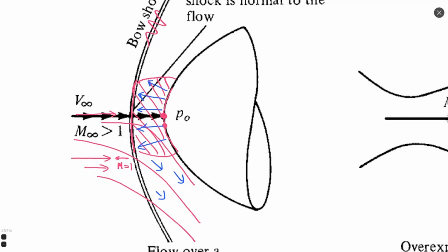We cannot see the volume of a shock wave. It's a thin surface or thin line, similar to the free path of a molecule, which is extremely thin in real flow. So we cannot say that from one point to another we have a transition of flow properties. We have a step function. We had one Mach number before the shock wave, and after the shock wave we have another Mach number immediately.